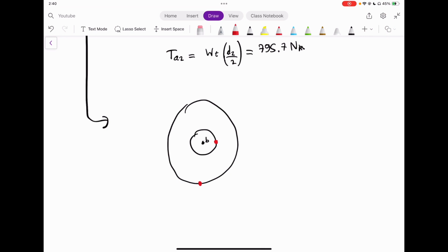And we can write the forces that we have. We know that the rotation of these 2 gears is counterclockwise. We have the 2 main forces attached to our system. The first is a force coming in from the bottom left, which is F23, the force from pinion 2 onto 3.